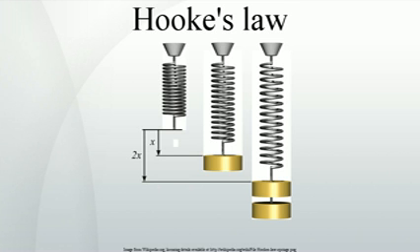In fact, many materials will noticeably deviate from Hooke's law well before those elastic limits are reached. On the other hand, Hooke's law is an accurate approximation for most solid bodies, as long as the forces and deformations are small enough. For this reason, Hooke's law is extensively used in all branches of science and engineering, and is the foundation of many disciplines such as seismology, molecular mechanics and acoustics. It is also the fundamental principle behind the spring scale, the manometer, and the balance wheel of the mechanical clock.